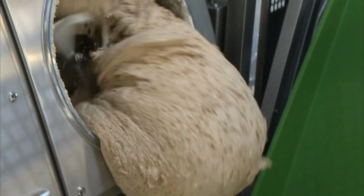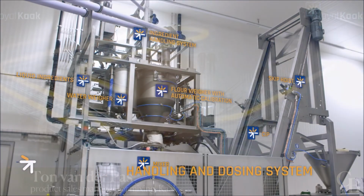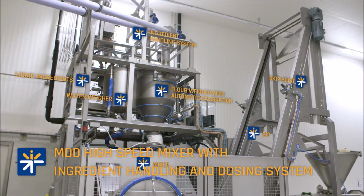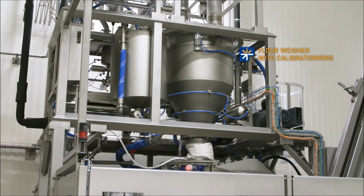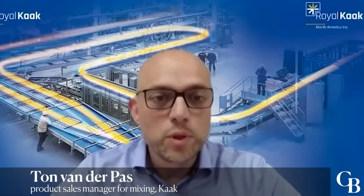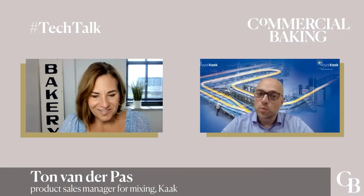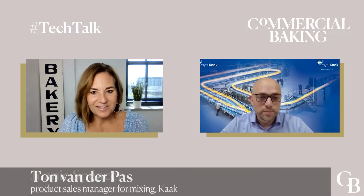We do that based on a measuring system. What we do, actually, is measure the amount of kilograms going into the mixer and apply the right amount of energy to it. So we are not mixing on time, but we are mixing on energy, what we call watt-hour per kilogram, or per pound for the States.